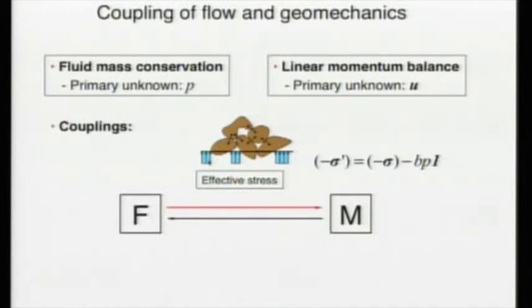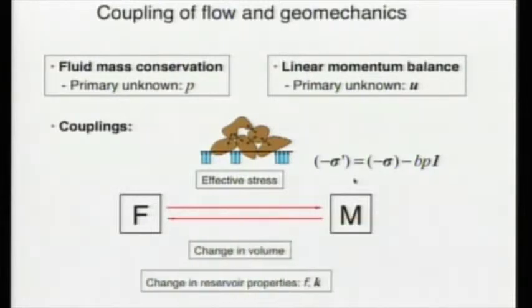There's a coupling between the flow and the mechanics, which is important because, as we know, when we increase the pore fluid pressure, we decrease the effective stress. Okay, so there's a direct coupling between flow and mechanics. But there's also a back coupling. When we change the stress, we change the volume. When we change the volume, we change all of the reservoir properties like the porosity and the permeability. Okay, so it's very good to have a model that can handle both flow and geomechanics at the same time.